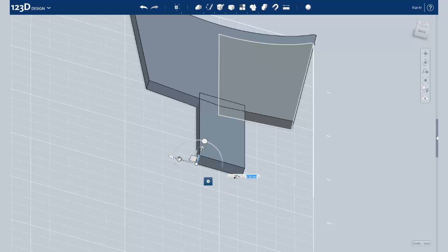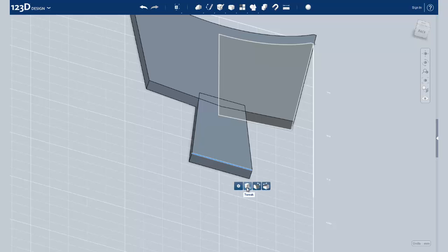The tweak function allows you to manipulate a section in various ways, and it can be useful when creating complicated geometries just like this one. Let me show you how that works again. I'll grab one of the ends and then move it over with the tweak tool 2 millimeters, which is the same distance as I moved the other side. And then I'll just click off the screen or push enter to accept the tweak. I'll do this for all the ends so that way we have our pyramidal shape.